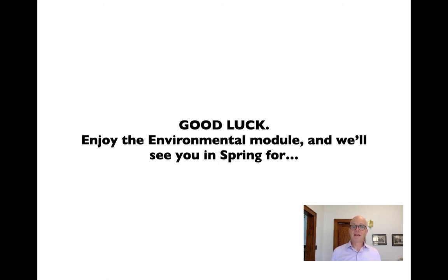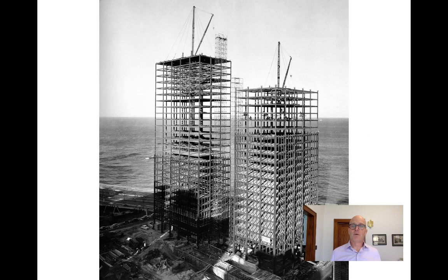When we come back in ARC 348, we'll take all of these elements and we'll look at the synergies that occur when we put them together. What happens when we attach columns and frames in ways that allow them to share some of the bending load or share some of the lateral load? Frames are a way of thinking about the way that we can build up resistance to gravity and to lateral loads into an actual coordinated system instead of just individual elements.